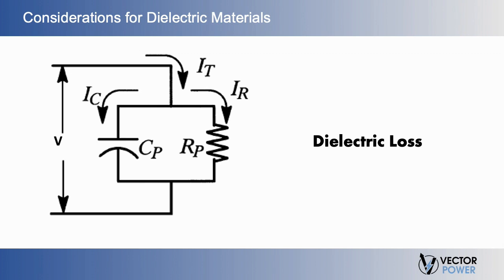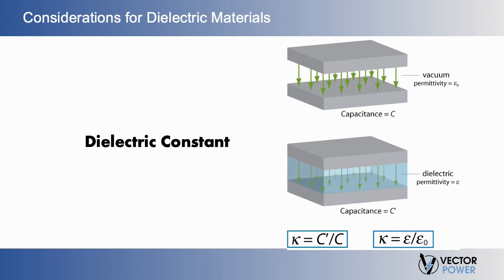Another consideration is the dielectric constant, the extent to which a substance concentrates the electrostatic flux lines. Substances with a low dielectric constant include a perfect vacuum, dry air, and most pure dry gases like helium and nitrogen. Materials with moderate dielectric constants include ceramics, distilled water, paper, mica, polyethylene, and glass. Metal oxides in general have high dielectric constants.